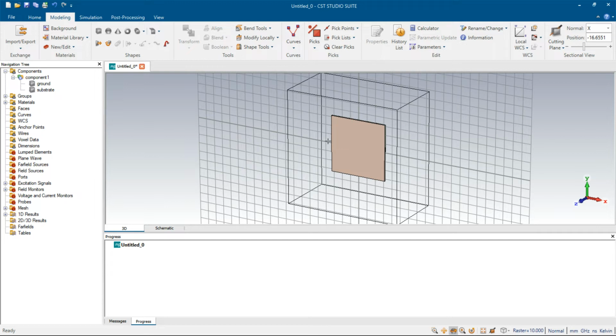And then next to this is the patch layer. Patch layer means signal, that is the topmost layer. So for the patch we have to define feed lines. To define feed lines we have to check the impedance matching. Impedance matching means the most efficient matching is with 50 ohm impedance. So for 50 ohm impedance, we have to select the feed line width and substrate thickness. Based on that only we achieve impedance matching. For that you can use online microstrip impedance calculators. Most of the websites, Radar Tutorial, Pasternack, like those websites are providing microstrip impedance calculators online itself.